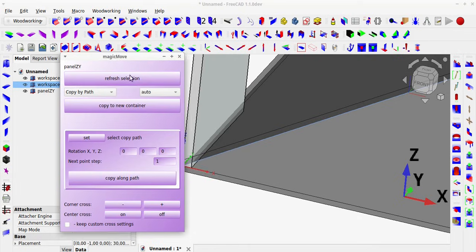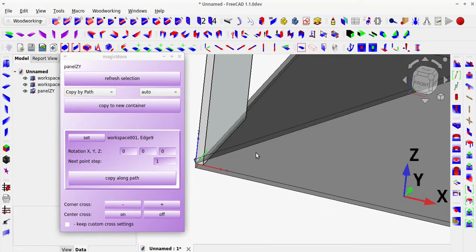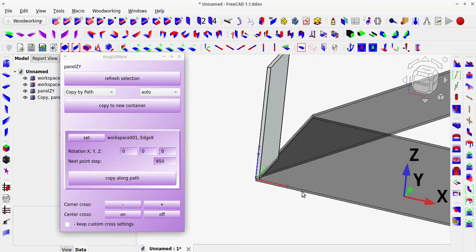The side walls of such a cabinet under a sloping ceiling can also be constructed with greater precision in terms of height and ceiling spacing. Since a sloping wall doesn't have an anchor point in the middle to extend the panel, you can do a little trick. First, simply create the walls along the bottom edge.